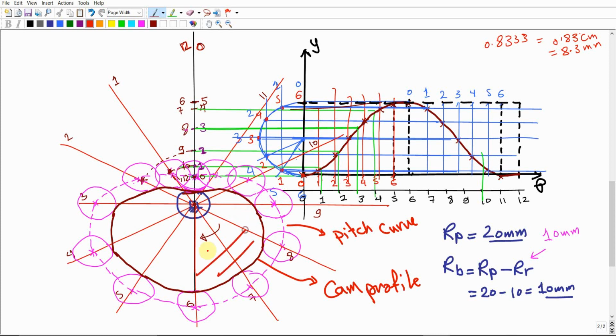And this thing in the middle is going to be the cam. Then once this cam rotates, it should provide a motion to the follower that can be described by this displacement diagram, as we did here. Make sense? So this is how we can generate the cam profile, and this is generally for the cam mechanism. And that's it, nothing else that I can add to this part.